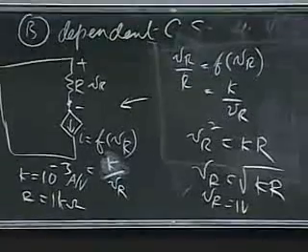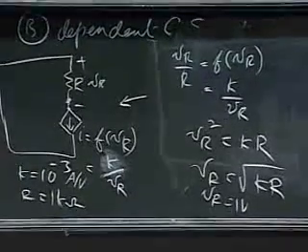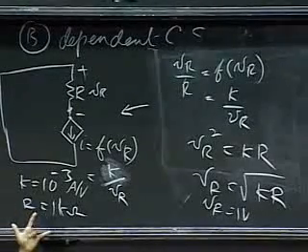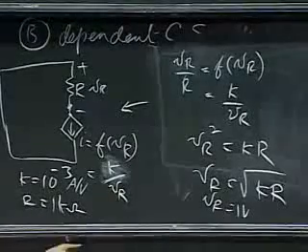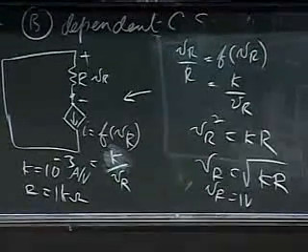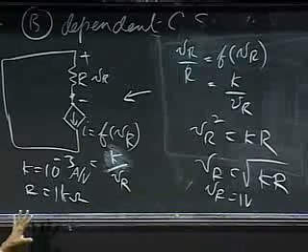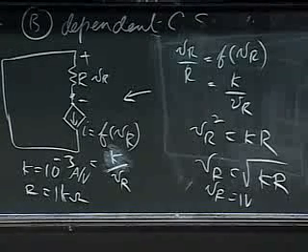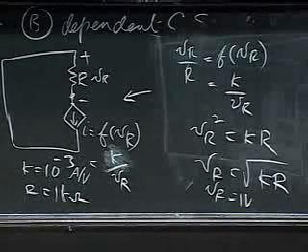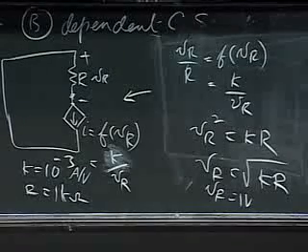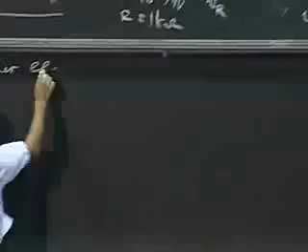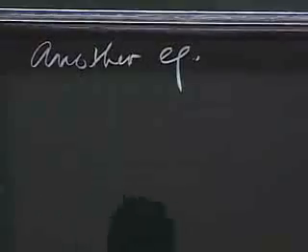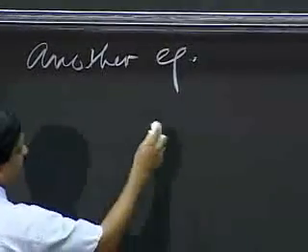So again, as long as you remember that the dependent source is simply another little circuit element, and you usually draw just the output port for dependent sources and reflect the way that the control affects the current, that will suffice, and you get, through the application of the node method, the variable you're interested in. So let's do another example, of another fun current source, a voltage-controlled current source, and look at it this way.